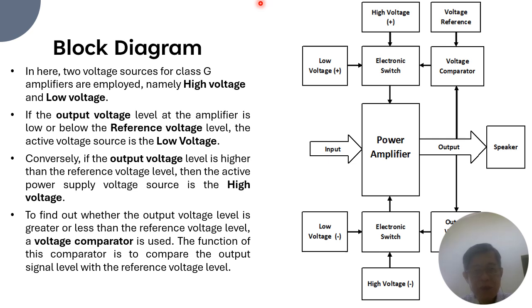If the amplifier input voltage level is large, after being amplified the output voltage level is also large, and the system employs a large power supply voltage so that the power dissipation can be kept relatively small. Why should the supply voltage be increased? It is because the amplifier supply voltage must be greater than the amplifier output signal, so that the output signal is not clipped or deformed. Therefore, the power supply voltage must be set greater if the output signal is increased.